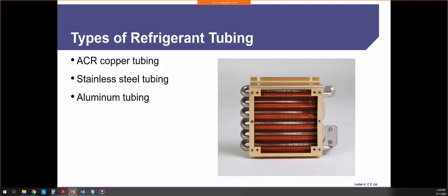All right, we have to connect our evaporator to our condenser. The evaporator is going to sit over the furnace. The condenser is going to sit outside. We need to have copper tubing to connect the two. What we're going to use is exactly what it's called: a line set. It's a predetermined length you can get at the supply house. It's going to come pre-insulated for the vapor line, and they're going to come in usually about 10 to 15 foot increments.